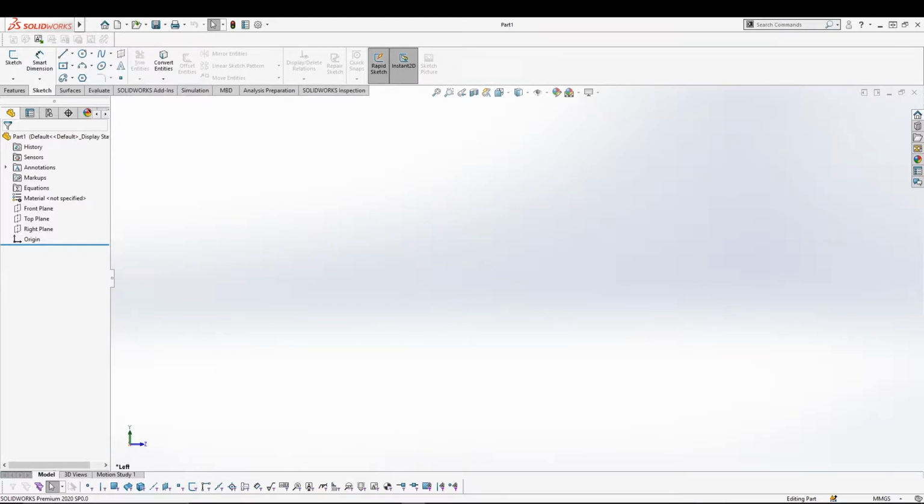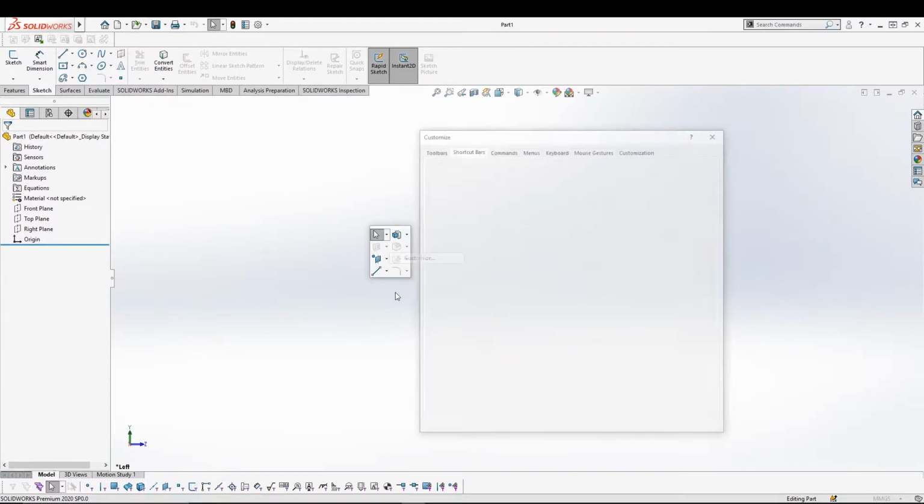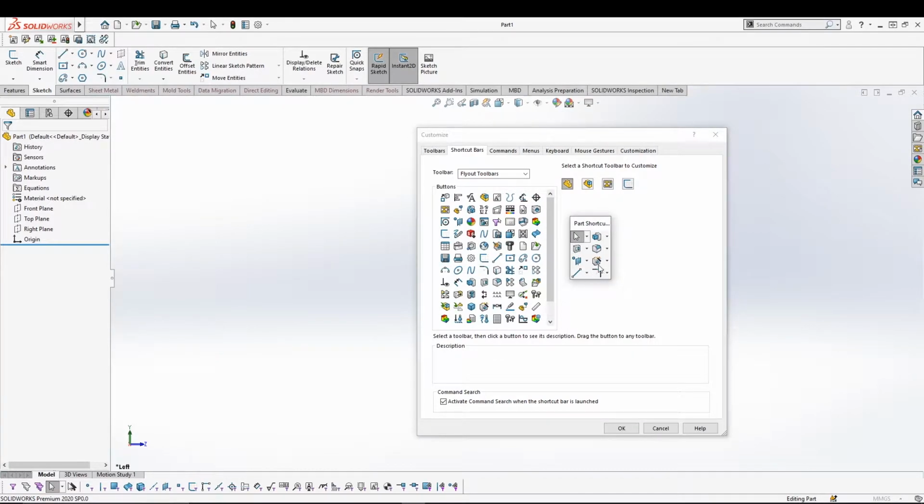The another shortcut tool that SolidWorks gave us is the S key. So every time you press the S key on your keyboard, you'll see this cute little window which has some tools. Obviously it has line, reference geometry, extrude boss. All these different tools can be customized as well. For that, just right click and go to customize, and you can pretty much add anything.